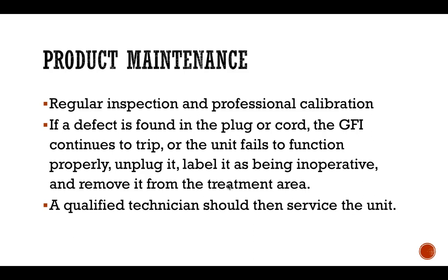If a defect is found in the plug or the cord, or if the GFI continues to trip, or something in the unit doesn't function properly, you don't want to keep using that. You're using that on a patient. So you want to unplug it, label it as broken or inoperable, and get it out of the treatment area so that it doesn't accidentally get used, and either send it in for service or have someone come out and service it.